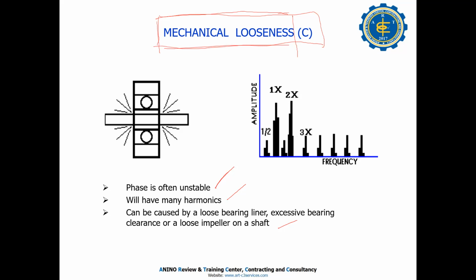If I have the software, then I know also your software. Maybe I can help you, or I can identify the sidebands, because the sidebands are always there if there is a problem. Normally in the bearing: inner race, outer race, gear frequencies, there is always sidebands. That's why I told you, in my experience with gearboxes,